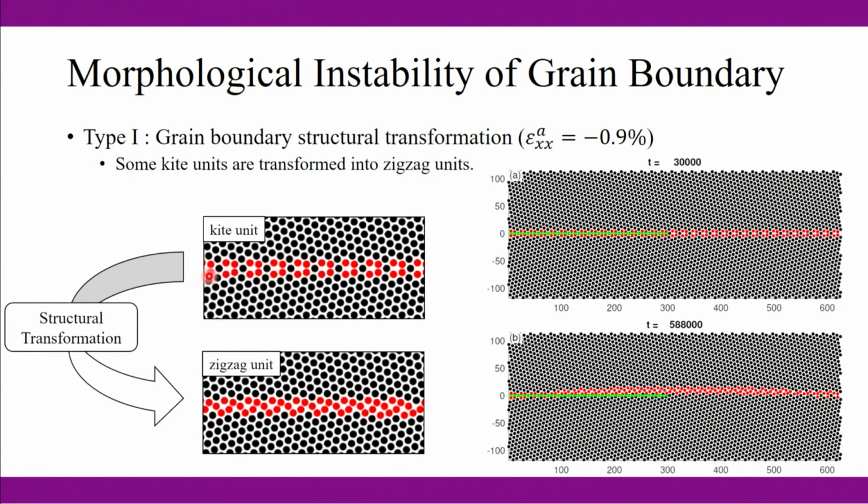For example, for a stress-free solid, you roughly can have this kind of kite structure. So if you look at what happened above and below, it's quite symmetric. But if now I start to compress, the spacing between those structures is going to become closer and closer. But since there's a compression or tensile, doesn't matter, the system is going to feel uncomfortable with that configuration. So the way they compensate is they can move around, maybe go above a little bit, so everything will shift a little bit. But the new configuration might lower the elastic energy of the system.